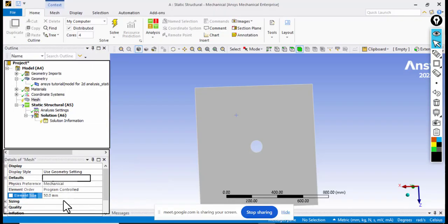It's trying to tell you how big that size is in this model. As I was saying, the default size was 120 something millimeter, and if I hover around the material or outside in the canvas, you see this circle that is close to my cursor. It was initially at 124.51, and I can see how big that 124 is relative to the model you are trying to mesh. So I'm going to change it to, let's say, 50 and click enter. Now I can see I'm okay with this size.